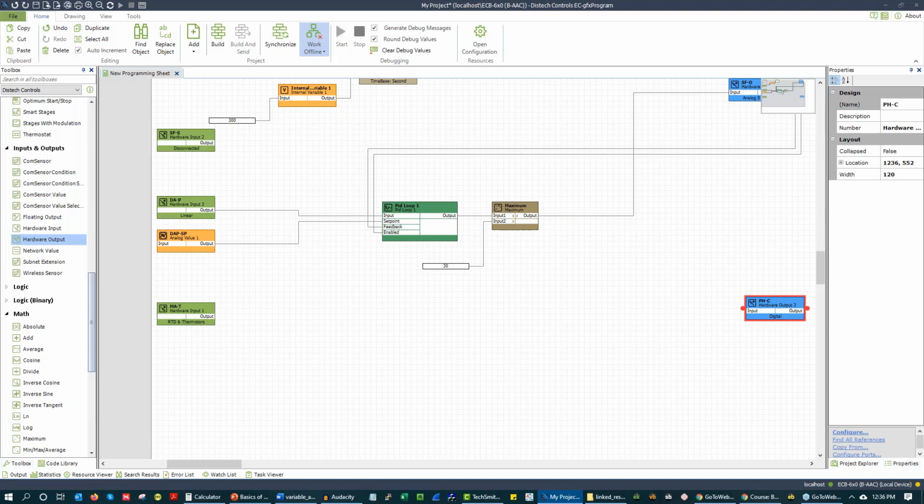And then Chad says, I think the sequence means the outdoor temp is less than 35, enable, and disable when it's greater than 40. I mean, that may be true, that there is a state between there. It's a confusing way to write it. I would use a table and I would make it very clear. I would just have a table there that would say enable, disable. So mixed air temp.